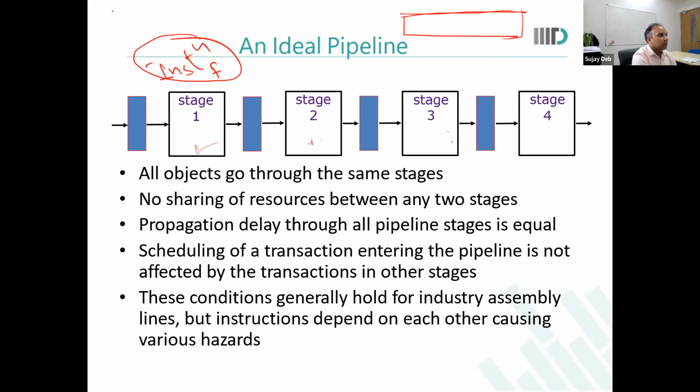So in this first stage, what I'll do is read my PC. What is the address stored in PC? After reading that address, I'll go to my instruction memory and find out what is the 32-bit instruction stored there. Bring it out. Basically, I'll read or fetch the instruction that I need to execute at this point.